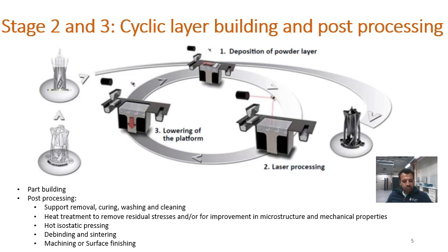This eliminates the residual porosity in the metallic components. It also has influence on the microstructure of the parts, and this is required when the parts are applied in critical applications, like in aerospace or in the case of medical implants, where the fatigue properties of the parts are very critical.